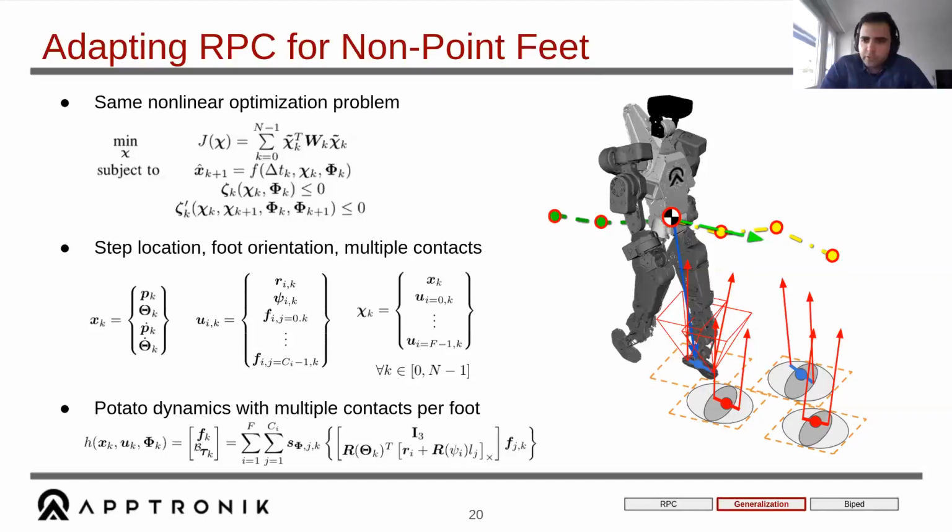Or maybe the question should be, do you predefine the gait sequence and the timings? Oh, yes. As far as the gait sequence of touchdowns and liftoffs, that's predefined. It's fluidly predefined. We do speed up the gait as the robot starts to walk forward faster, and slow it down as the robot's more stable until we reach a standing speed, and then the robot stops moving.